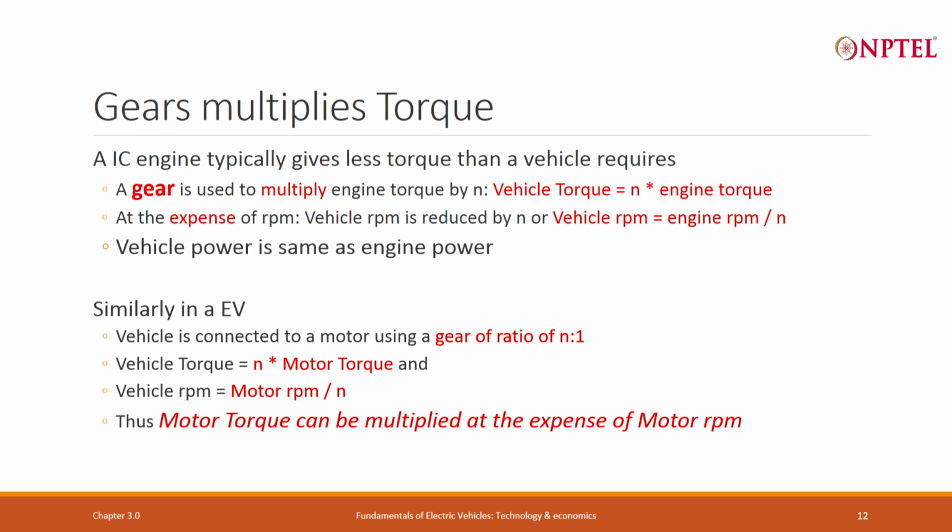Well, there is always a gearbox efficiency, which I have not taken into account, which I will leave to motor people. EVs normally use a single gear, n is to 1. As was pointed out, there is a certain efficiency, which can be 98%. So, very close to 1, we normally will assume 1 unless it is required. If there are multiple gears, the efficiency gets worse. A single gear is almost fully attached, and you can get very high efficiency, 0.99, close to that.